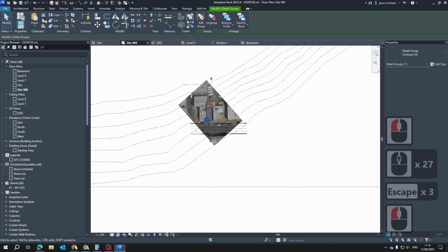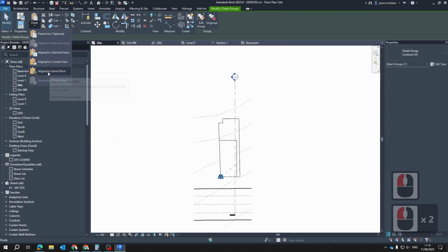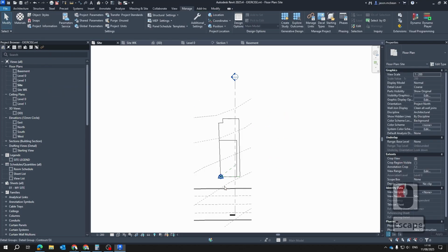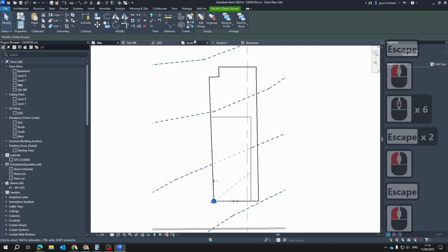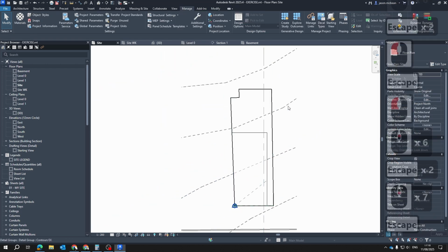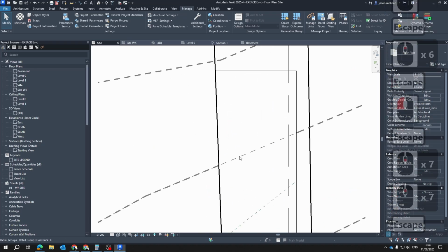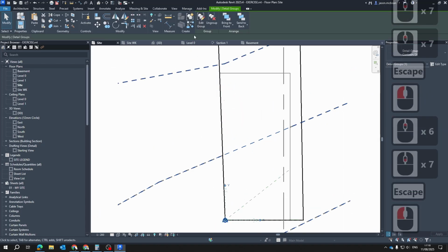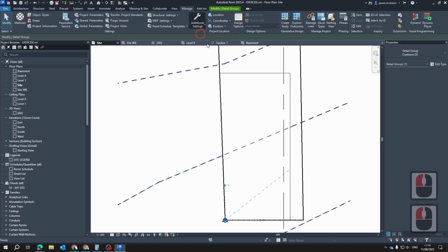I'm going to copy this information, copy, go back to site and paste, aligned to current view. Good. So now we should have our contour information above. Okay, I did make a slight mistake on my contours. I maybe want to up the line weight of these to line weight 5. So I'm going to go and say manage line types. I'm going to go additional settings, line styles.